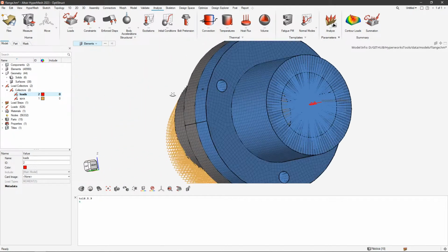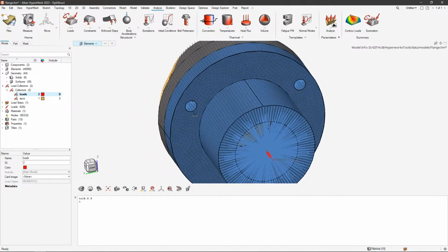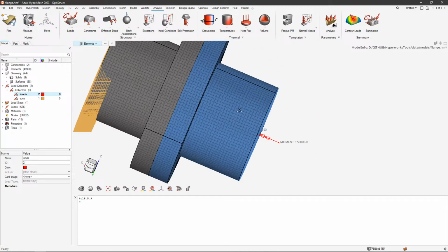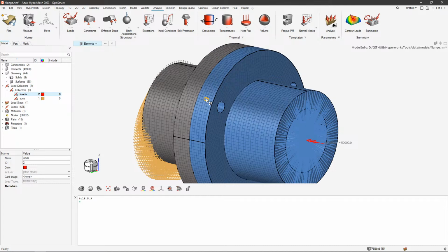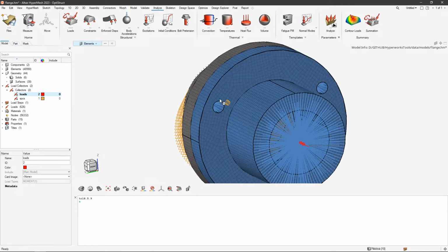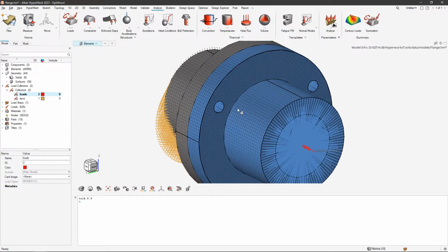And these are the RBE2s here. This is modeling rigid bolt connections, right? So nothing with a stiffness, just rigid bolt connections. And the tool is being used to identify how much force is being transferred for which of the connections. Now, we started with the neighbor detection thing.